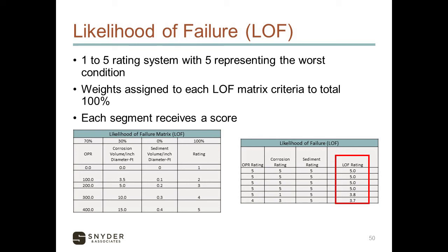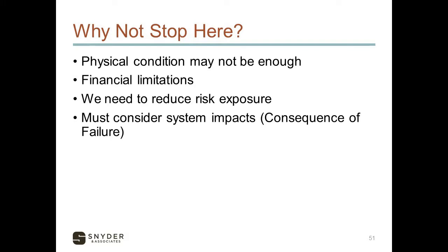Essentially, each asset that's inspected from manhole to manhole gets run through this matrix, and then the likelihood of failure rating is calculated based on those percentages. So why not just stop here? In some cases, you may be able to, depending on the size of your system or your goals.